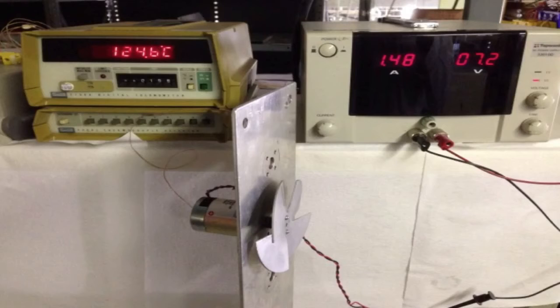Once the motor is mounted to a plate, additional heat transfer will occur. Most of the heat is conducted through the mounting contact between the motor and plate. You can see this reduce the internal winding temperature by 25.6°C.